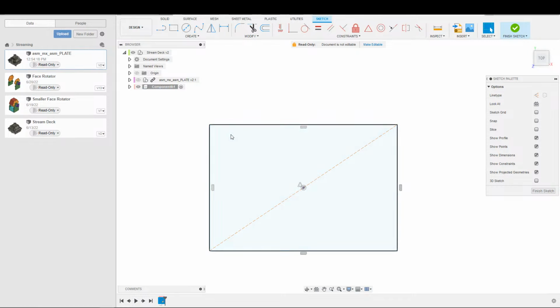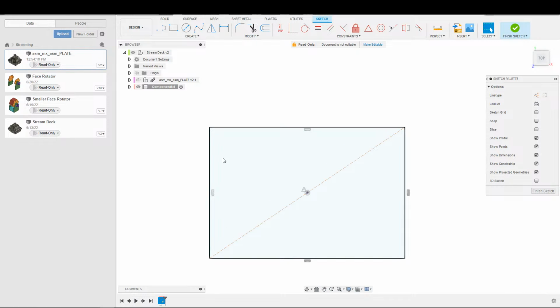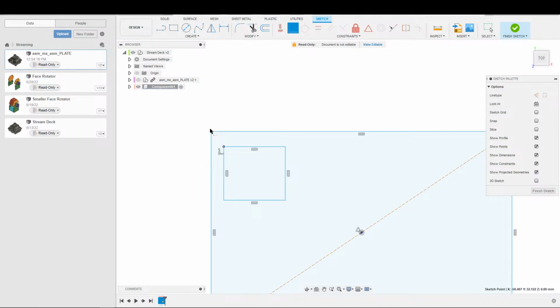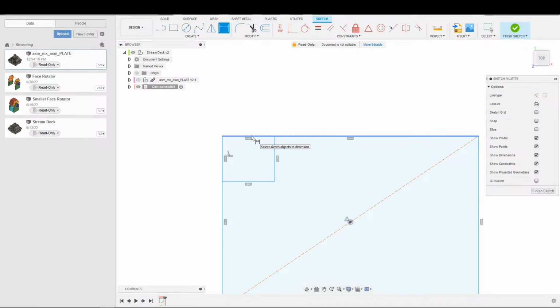And actually, I don't really even need this because I'm just going to extrude that out. You know what? I'll put this one in here anyway. And we can take this up to the corner because this number has our size in it, which is not keycap size, it's switch spacing. So the overall size here already has some buffer around our keycaps, or around our switches anyway. So that's why I can do this in the corner. We'll have meat because we're only going to cut out. Actually, let me go ahead and cut that out right now. Spacing.